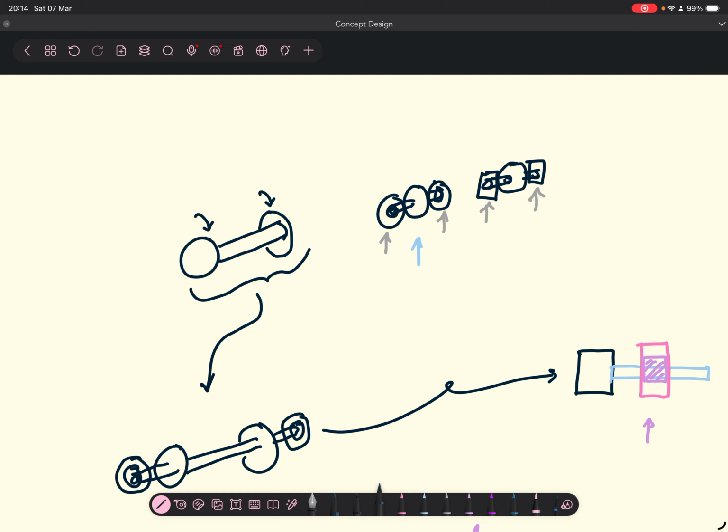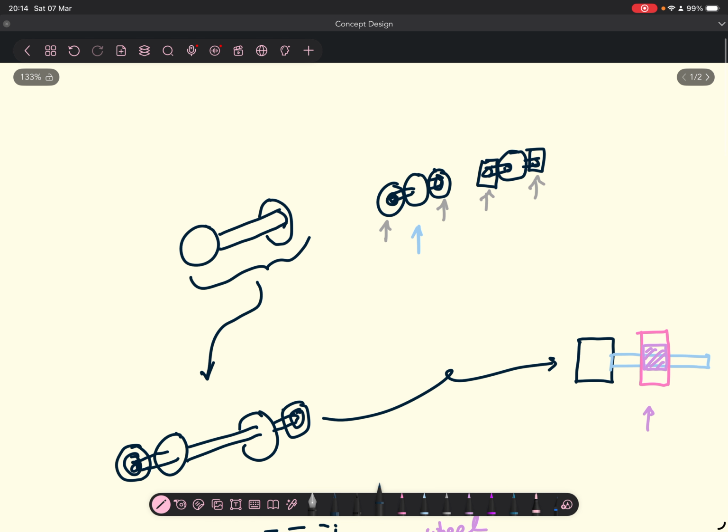You're going to have a lot of vibrations, which you don't want, right? So one very easy way to mitigate any misalignment is by making it shorter, so that when people are manufacturing it and assembling everything, it's less prone to human error, and it's a lot easier for them to do.